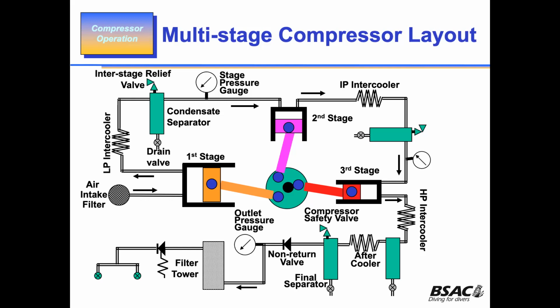So we just compress the gas over a number of stages, and in each stage, we take the pressure up in stages by reducing the size of the cylinder. At the end of the day, what you're pushing out on the third stage, volume-wise, is very small.